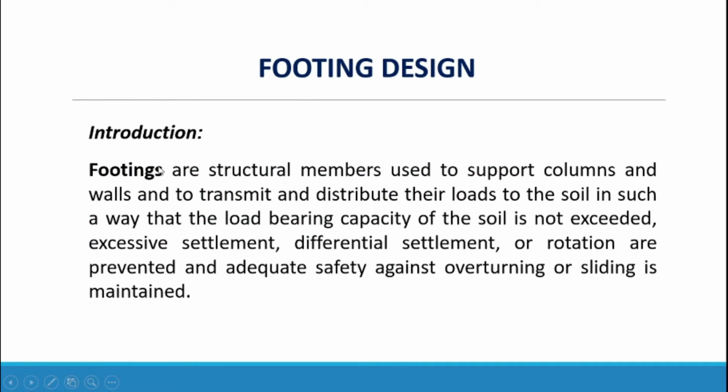Footing design. Introduction. Footings are structural members used to support columns and walls and to transmit and distribute their loads to the soil in such a way that the load-bearing capacity of the soil is not exceeded. Excessive settlement, differential settlement, or rotation are prevented, and adequate safety against overturning or sliding is maintained.